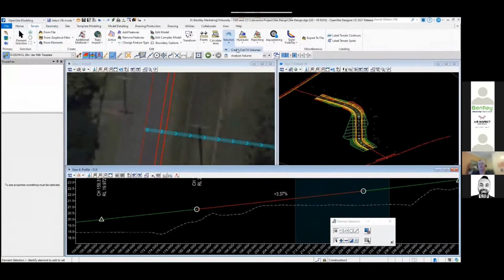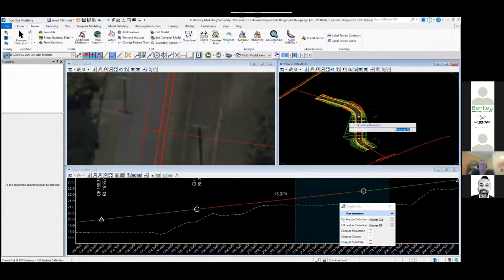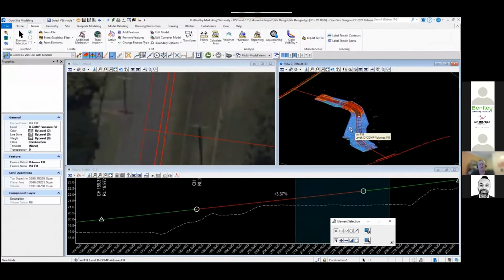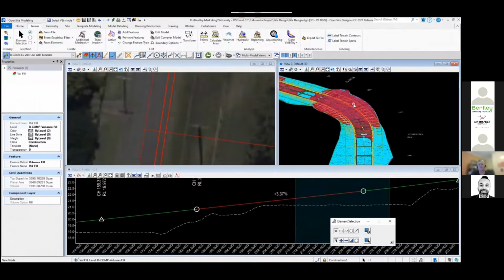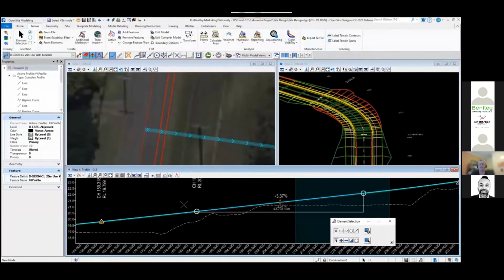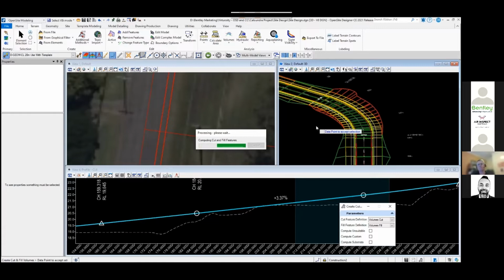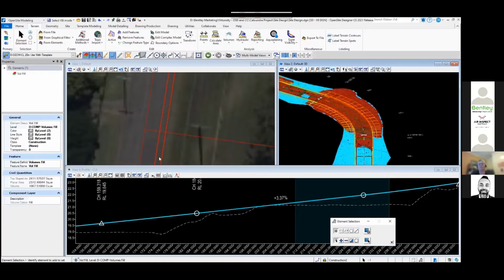Now, at this point here, I'm also conscious of the fact that I don't want to have to import material in for cut fill, and I don't really want to export a lot of cut fill material. So I'm going to come in here and calculate the volume of cut and the volume of fill. And I'm going to manually iterate my profile to try and balance out that cut and fill. And we're just talking about the subgrade material here. So we're not looking at the base, the sub-base or the asphalt. We're just strictly looking at the subgrade material, the cut and fill material.